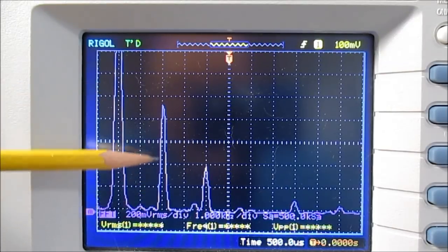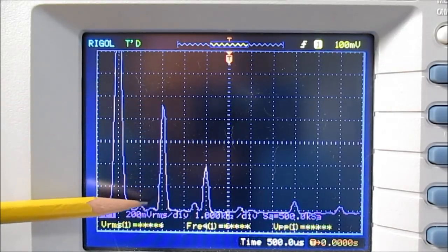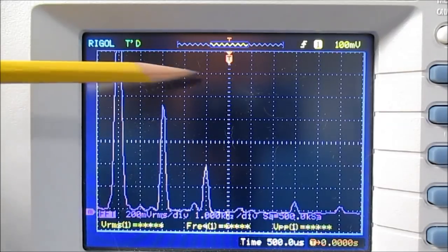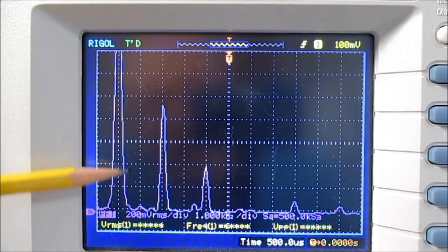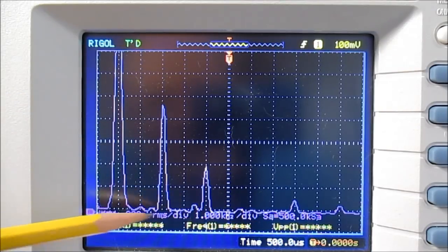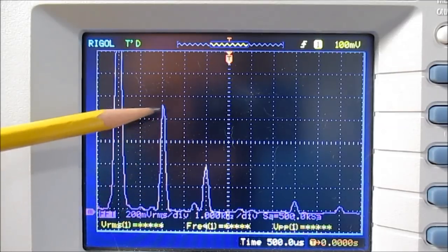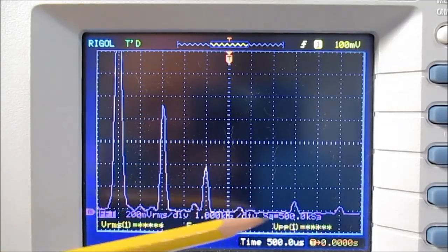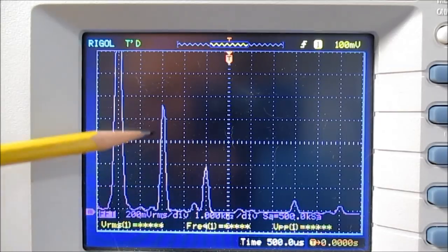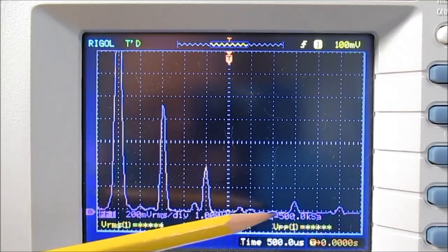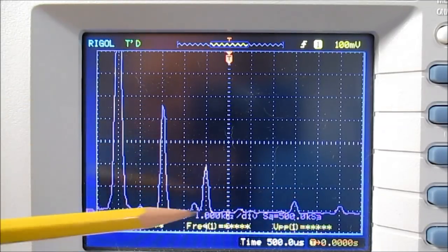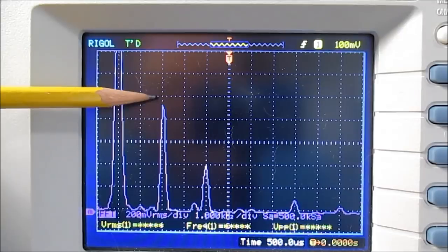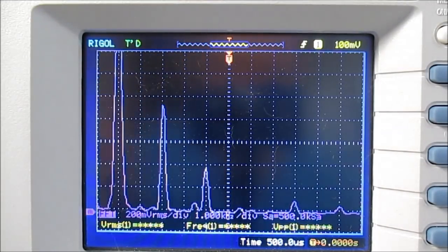And we're getting a big third harmonic spike. It's third harmonic because it's clipping on the top and bottom. So that would be indicative of symmetrical clipping. And there's not really any other harmonics except for that. Maybe a couple small notches, and those will add into a little bit of the total. So we'll just eyeball it, set it a little bit less, and we'll just call that 10%.